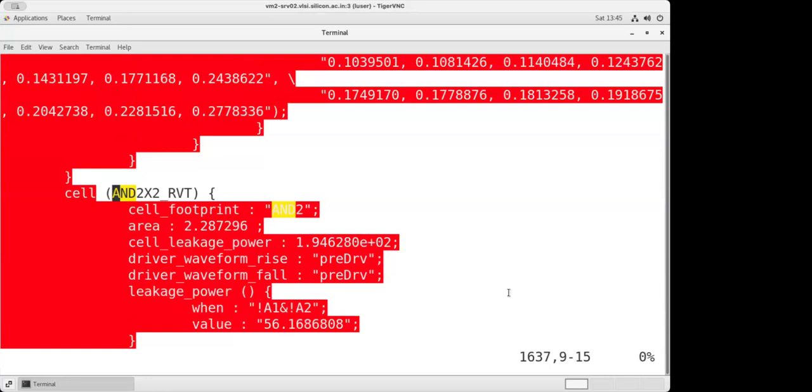What is the difference? Maybe sometime later we can discuss this part. But that means in the same file there are two AND gates. Those two AND gates are of different types, with different properties: different delays, different power, different area. Based on the constraints which we have seen as part of the specification, the tool is going to map it to this one, the previous one, or any other AND cell. So there is a linking of the libraries with respect to the circuit.